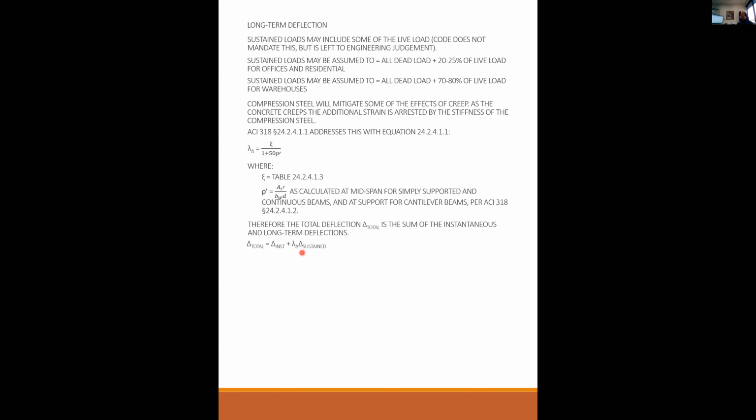Then, and I forget when that was built. I guess if somebody is looking it up, maybe you could tell me, but I think it was in the 30s. Was it the 30s or the 40s? That is a long time ago. And after being in service for something like 60, 70 years, that deflection, 1939, thank you. That deflection then was closer to 6 or 7 inches after all that time. Why? Because concrete creeps. So what started as like 2.5, 3 inches is now closer to 7 inches.